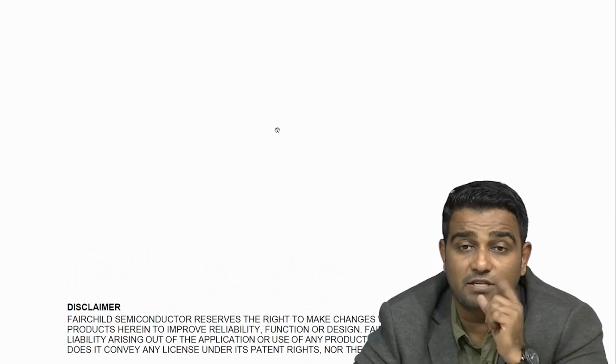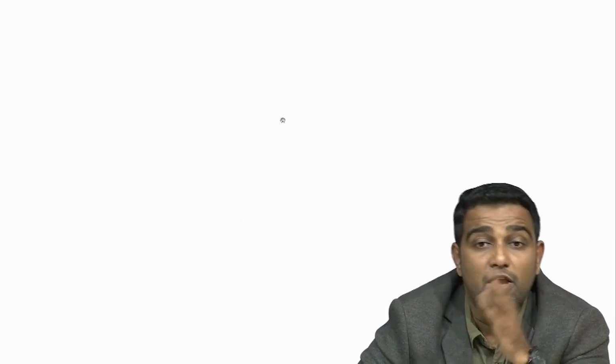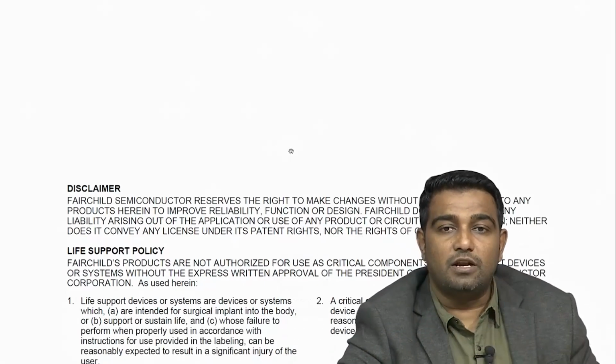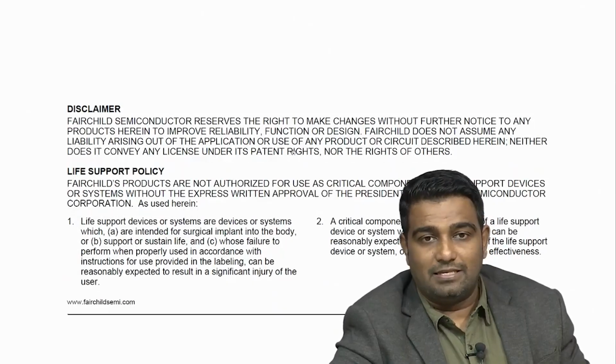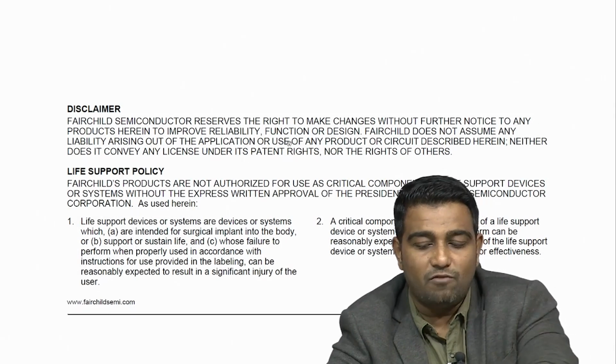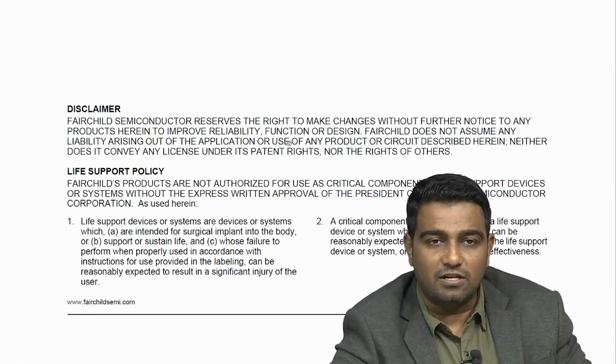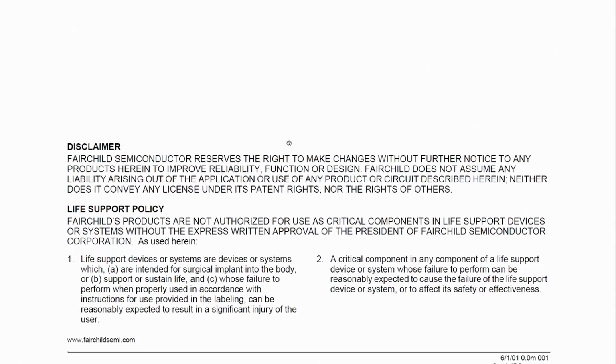Like we have discussed earlier: input bias current, temperature compensation, power supply rejection ratio, common mode rejection ratio, input offset voltage. Then we have the operating frequency, how the input resistance would change, and how the output resistance will behave with respect to ambient temperature. These are all the things you have to understand when you are looking at the IC. Now, since we have seen what the data sheet generally gives us, this is the end of the data sheet, as you can see here.